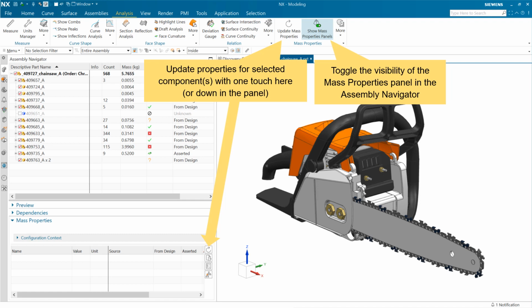We're going to Parasolid for a variety of detailed mass properties there, and depending on the amount of geometry, either in terms of a large assembly or very complex components, that mass properties calculation with high precision can sometimes take several seconds. And so as a result of that, we've chosen very intentionally to have this be an update that's user initiated here. So we'll let you do that very easily.